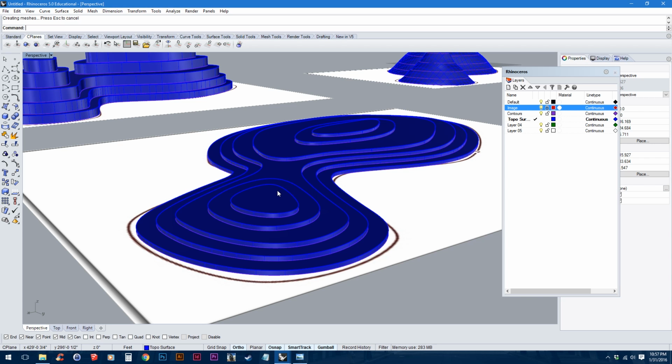You want to be able to edit the terrain a little bit easier than if you were using the patch command, because with the patch command you have to adjust the contour lines and then redo the patch command. So I've showed you 2 different commands, the patch command and then just using the extrude curves to extrude the contour lines up and making each one a flat surface.